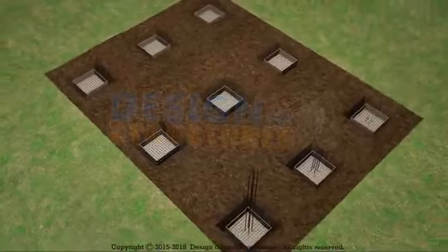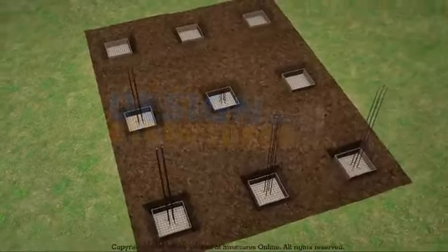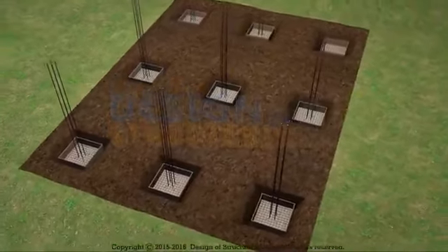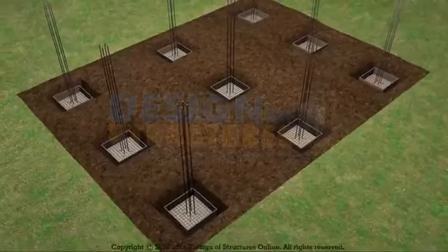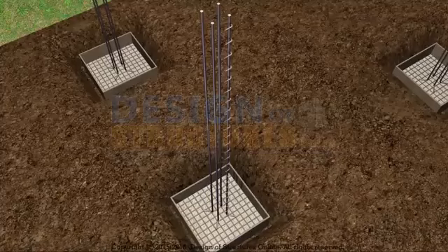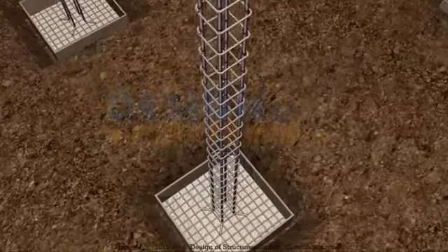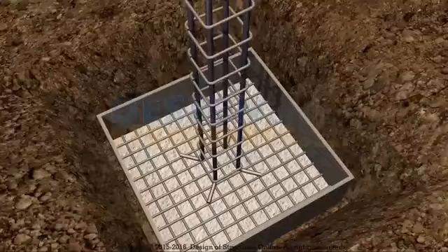Reinforcement shall be as per the bar bending schedule prepared according to the drawing. The reinforcement shifting and binding shall be started as soon as shuttering is completed. Reinforcement binding shall continue as shuttering work progresses.